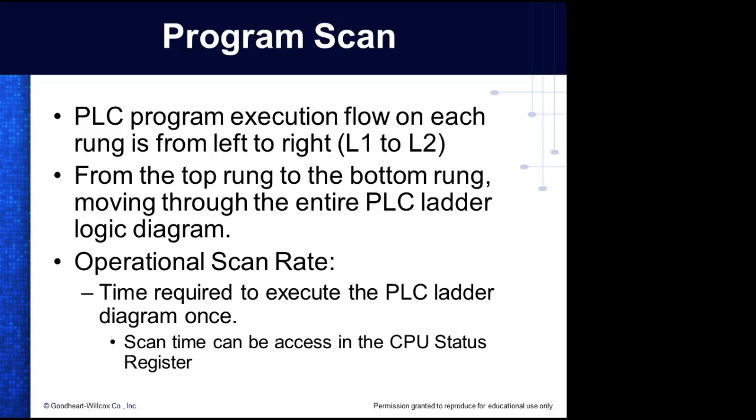So a scan would be like me, you know, starting with Gary and going back and forth, saying, do you have anything for me? Do you have anything for me? An interrupt would be, I'm up here talking, I'm still doing a scan, but you need to get my attention, and you do what? That's what computers allow us to do. So now you can assign extremely high priority inputs to these interrupts.